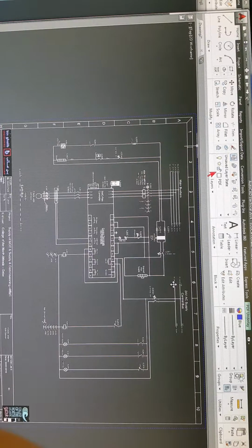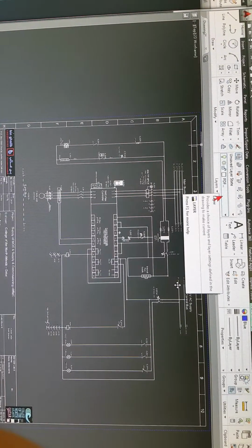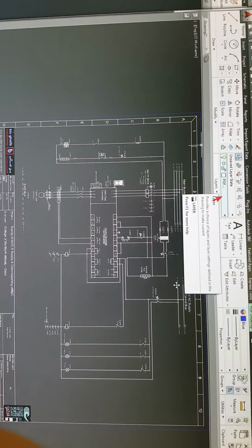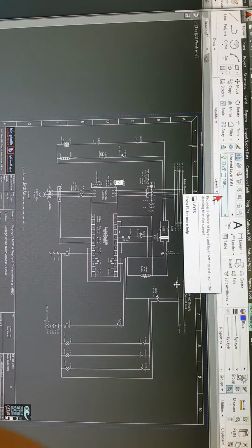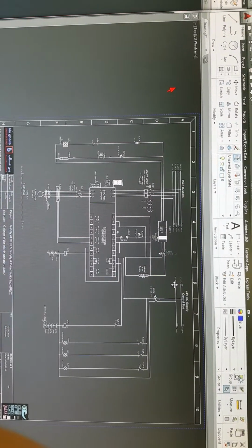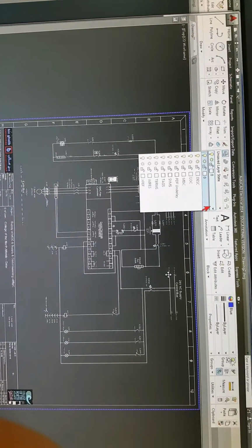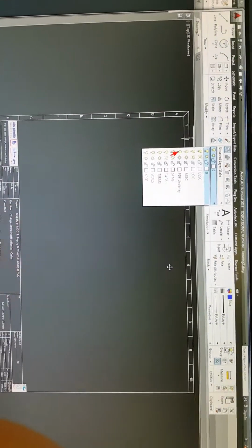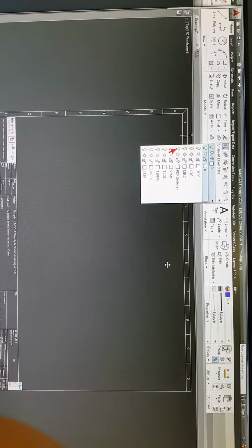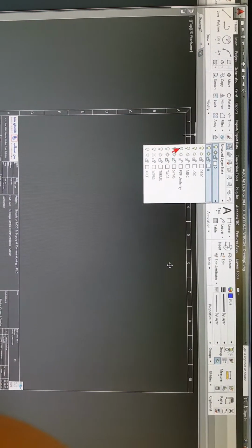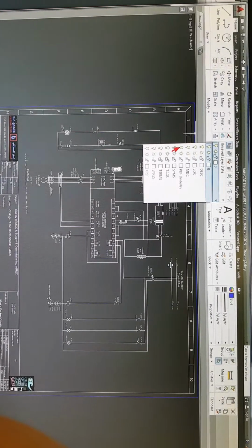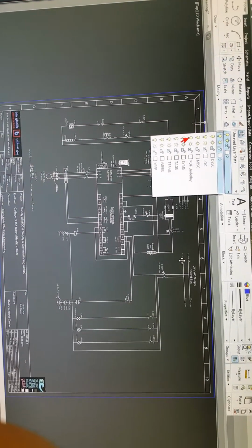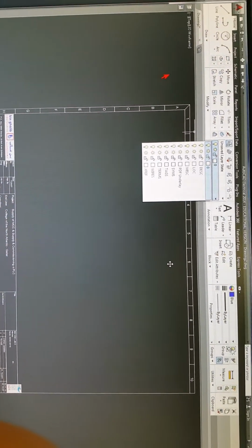Again, by now you should know how to use layers, how to select, how to turn off, how to turn on, how to create, how to delete. Everyone okay with that? So now if I go back to 0 and go to the drop-down menu and turn off my PDF layer, the image disappears, but it's still there. If I turn it on, it's still there. You don't have to move it anywhere, you don't have to delete it temporarily. So, turn it off.